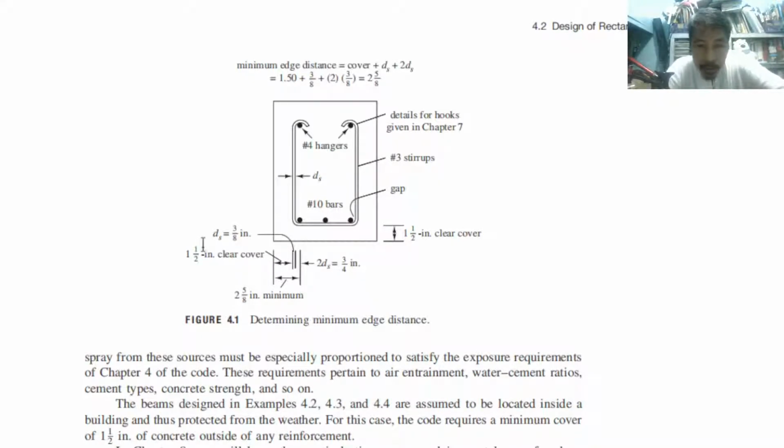So we have stirrups, number 3. Number 3 stirrups here. So this is what we call a stirrup. The black dots are the reinforcement. These 2 dots above are the top reinforcement. Bottom reinforcement, okay, is also called tension reinforcement. These are compression reinforcement. So this steel bar is what we call a stirrup.